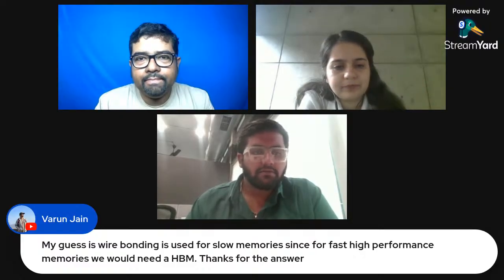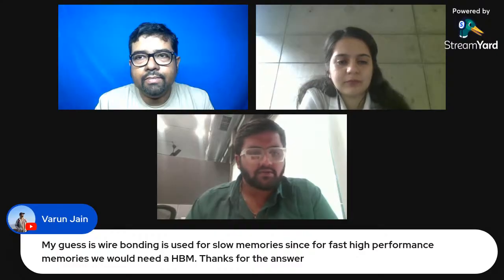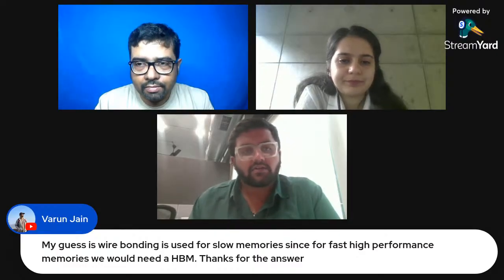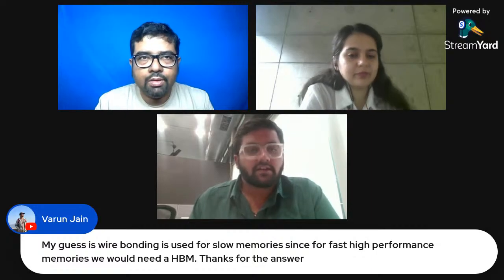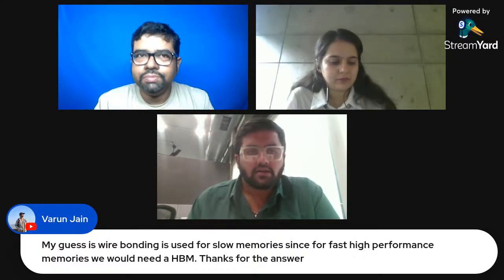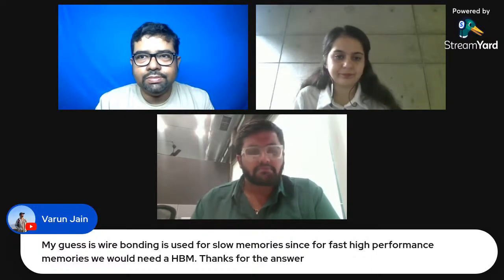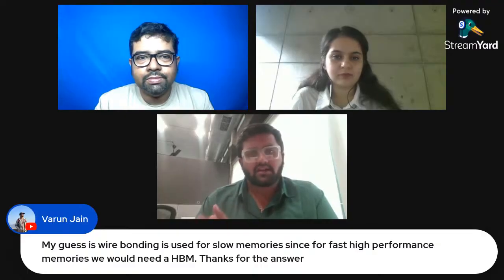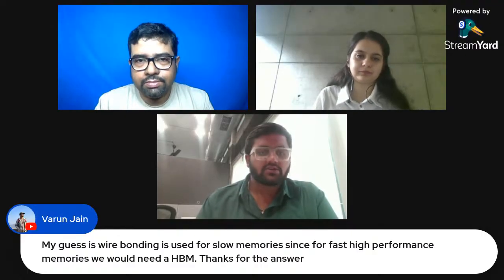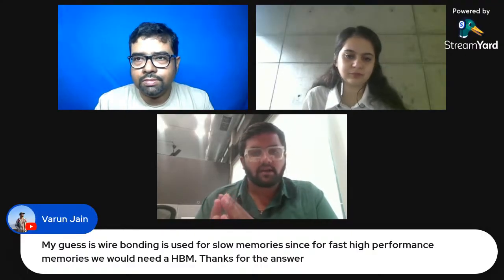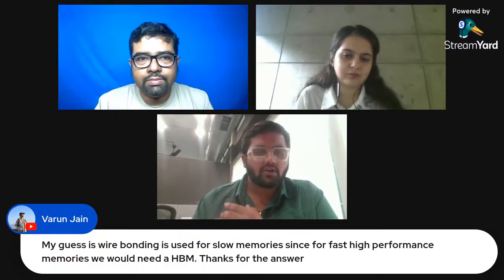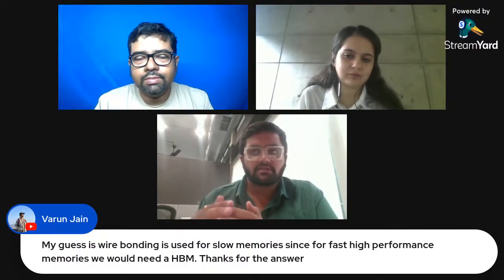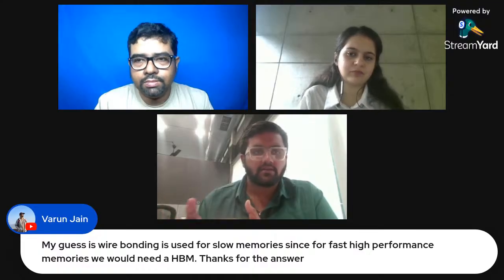Yeah, it's true. For memories, it's wire bond, but generally now they are converting to 2.5D and 3D packaging, even for wafer level chip size packaging. So wire bonding can be used, and there are different ways to make sure the memories are high performance and fast. So it can also be a similar way to do the packaging for memories.